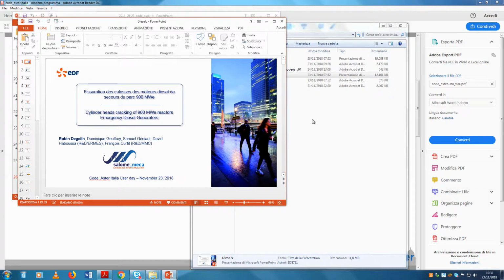There's CAE Linux that distributes a specific version that has Salome-Meca inside of it, but of course it's not in parallel. And often you need to compile it. If you go with the binary version directly, since the architectures are not the same, I think you lose most of the efficiency of the MPI processes. So, yes, compiling a code in parallel is complicated. I know it. Personally, I can do it. I have people in my team that do it, but it's complicated.